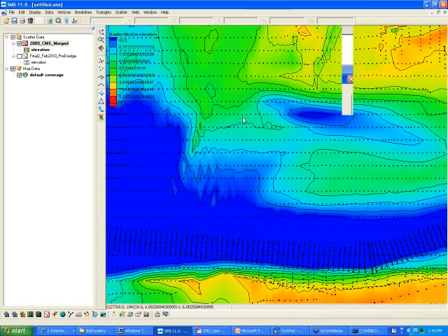The model does not calculate bed forms unless you have maybe 20 cells per bed form length. And if it doesn't have that, then it's just noise to the model, and they're going to smooth it out. And when you calculate bed change, that high resolution noise is going to turn up as noise. It's going to look like you're going to have a lot of reds and blues.